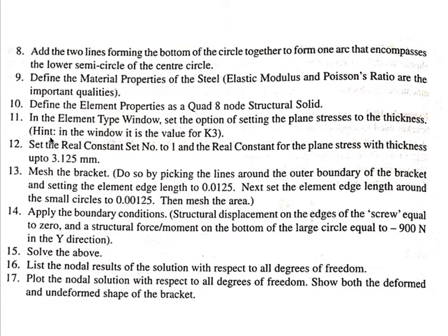If you see that hint in the window, it is the value of K3, we'll get over there. We'll see this in the software even. So just go through this procedure how it would be. We will particularly look into that on the software. And then set the real constants, set number to 1 and the real constant for the plane stress with thickness to 3.125. That you have set.